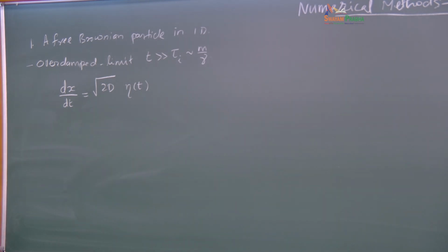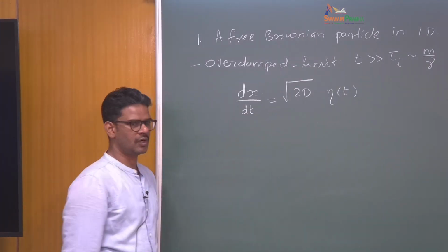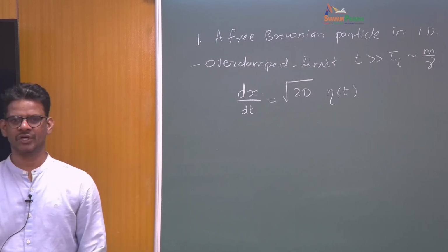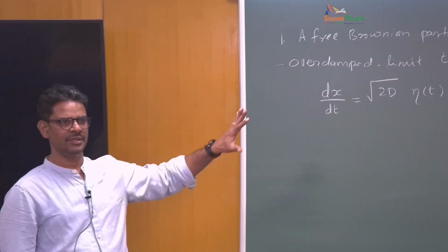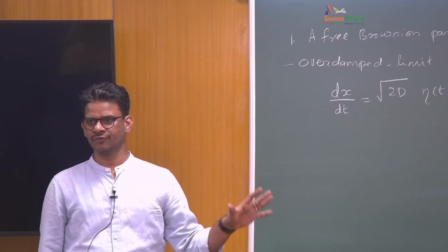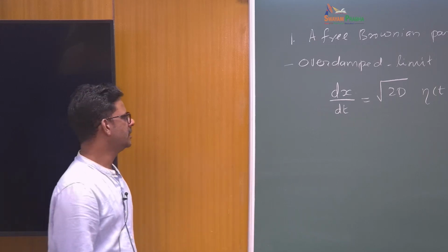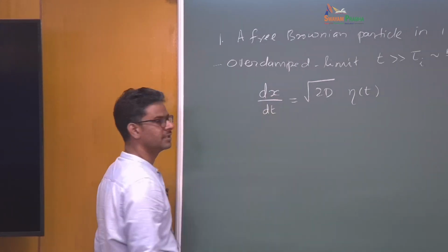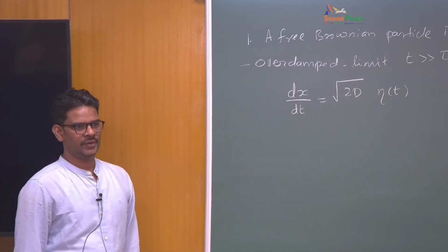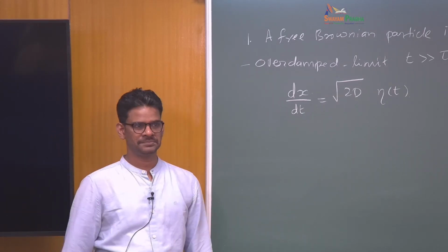Now what we want to do is construct a very simple numerical technique for solving this numerically in a computer, and before we do that we can think of non-dimensionalizing this equation so that all the parameters can be kept as some sort of groups of non-dimensional numbers. Okay, so here we have this x, which is a length scale, and what's the natural length scale in this problem?